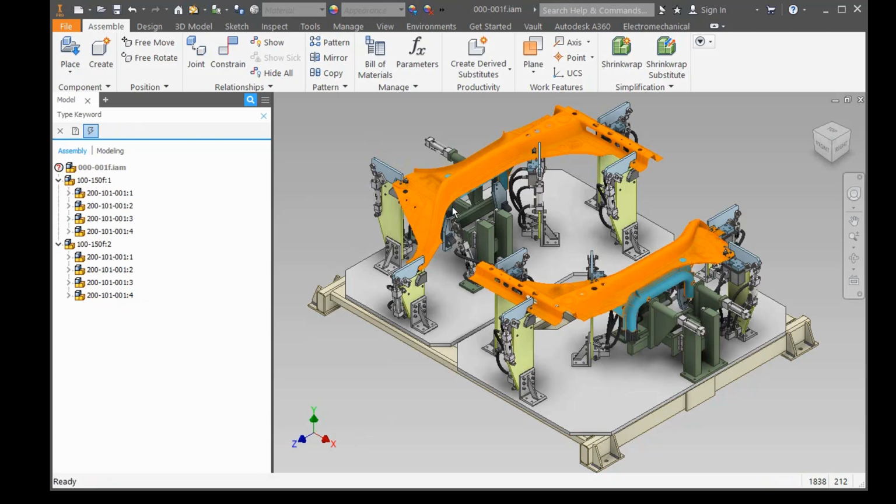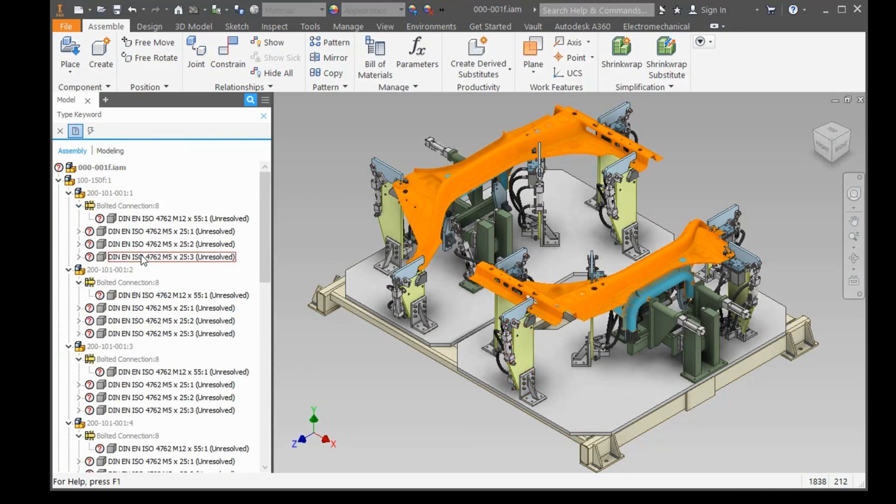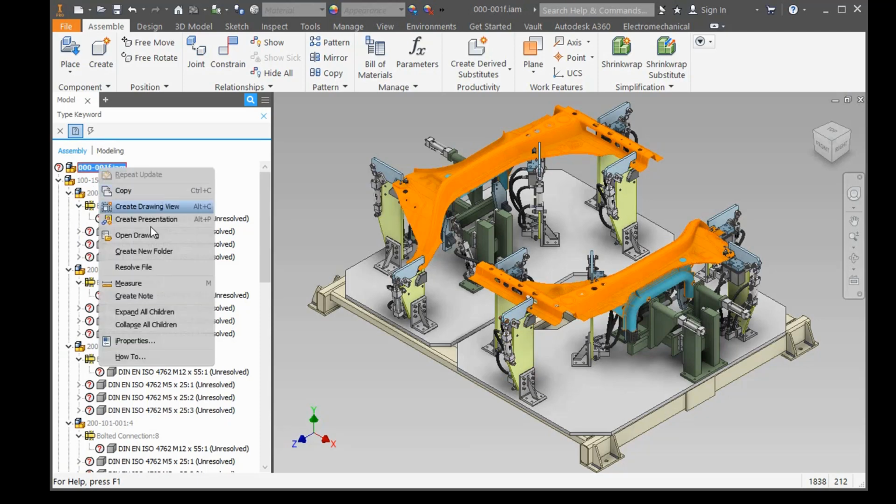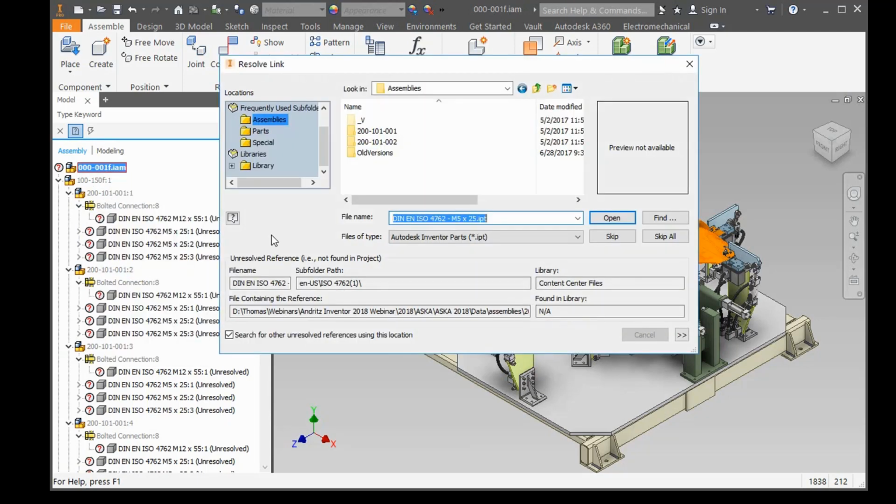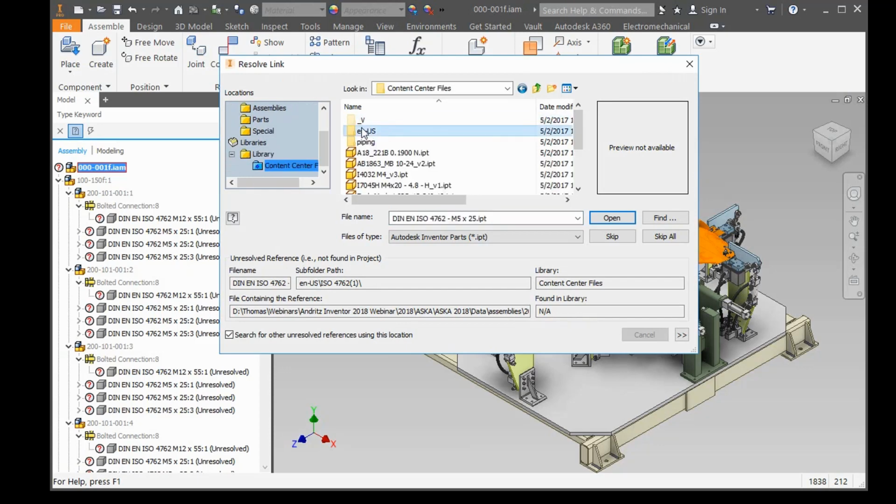Further, I urgently need to know what components are unresolved as the performance is limited by those components. With a click on the corresponding filter button, I get the unresolved components. As my CAD standards require Inventor datasets to be fully resolved, I take care of the missing part.